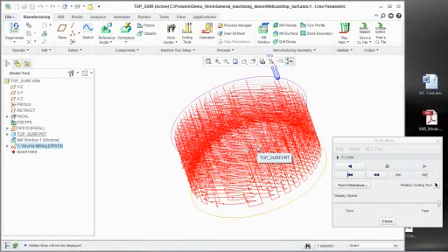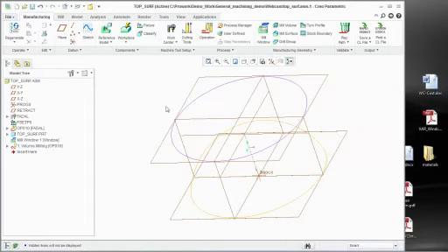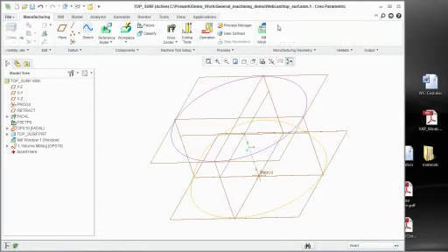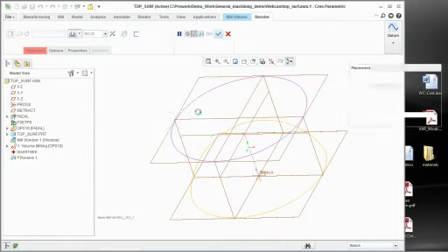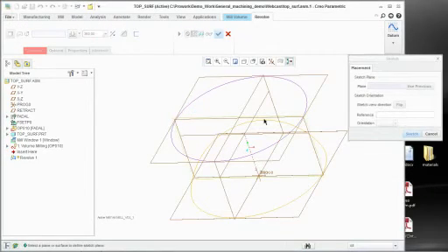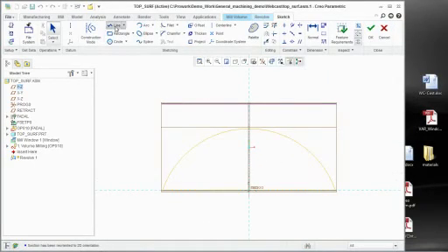And if you were machining out a big giant block, this is perfectly fine, but not everybody does that, okay? So what you have the ability to do in a voluming toolpath is conform your shape, or the top shape of your toolpath, to the shape of what would be something called a mill volume, okay? And what I'm going to do in the mill volume is I'm just going to come in and create, in this case, a fairly rudimentary shape that emulates what my casting would be. So I'm just going to come in and say, this is what essentially my casting would actually look like.